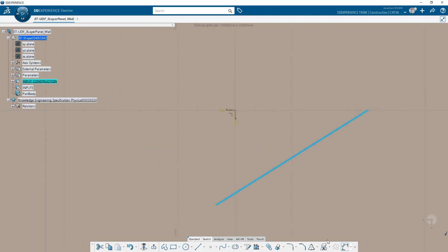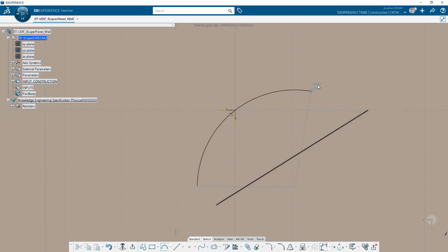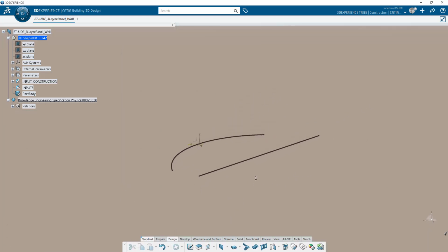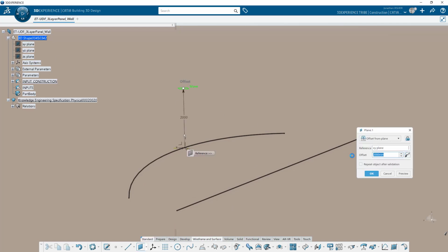They're similar to power copies as they are parametric components that encapsulate parametric geometry that can be reused then across different models. We'll start with the inputs. These two lines are going to be the support of a mid-surface. When we're creating a wall object type that is compatible with the new building features in Building 3D Design, they can take a mid-surface as an input, an envelope surface, or a wall body. Here we're going to use just the mid-surface.